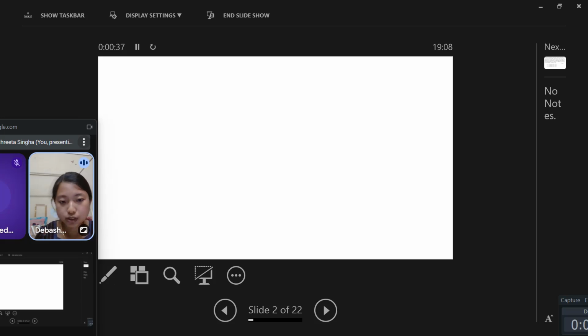So for fully developed flow, the temperature profile does not change. It remains similar. So del T by del X is equal to dTm by dx is equal to dTs by dx. So all this you know. So for constant flux problem, dTm by dx is equal to minus Qs into perimeter divided by m dot Cp.